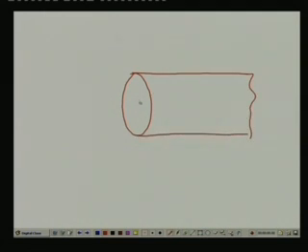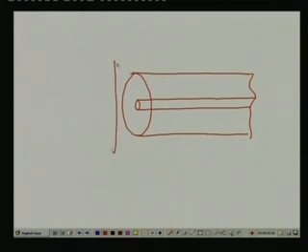In the single mode fiber, the core diameter is extremely small. So, that is the problem; we need different sorts of sources here, directional sources. The light will travel, and in this case the refractive index profile, if I plot the refractive index Ri, will look like this, I have a small change here.